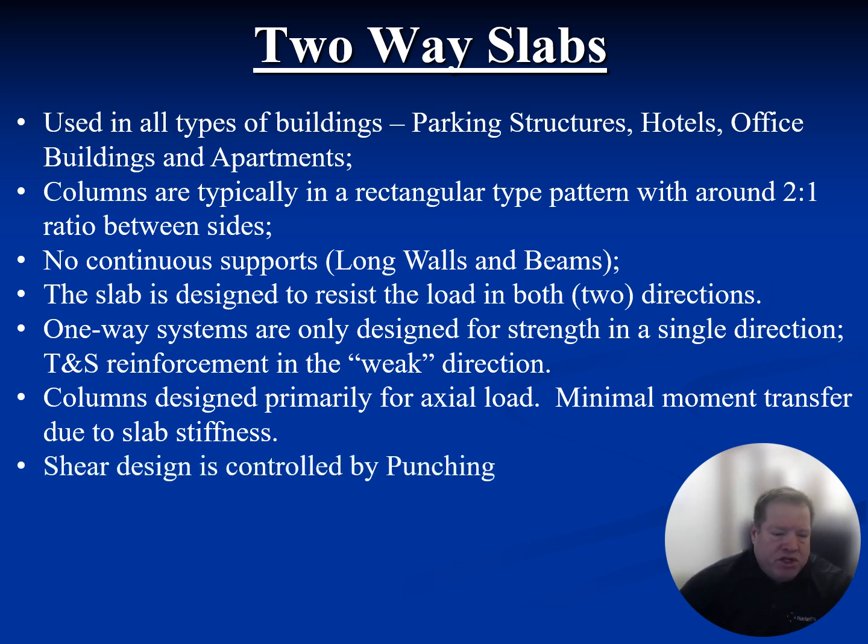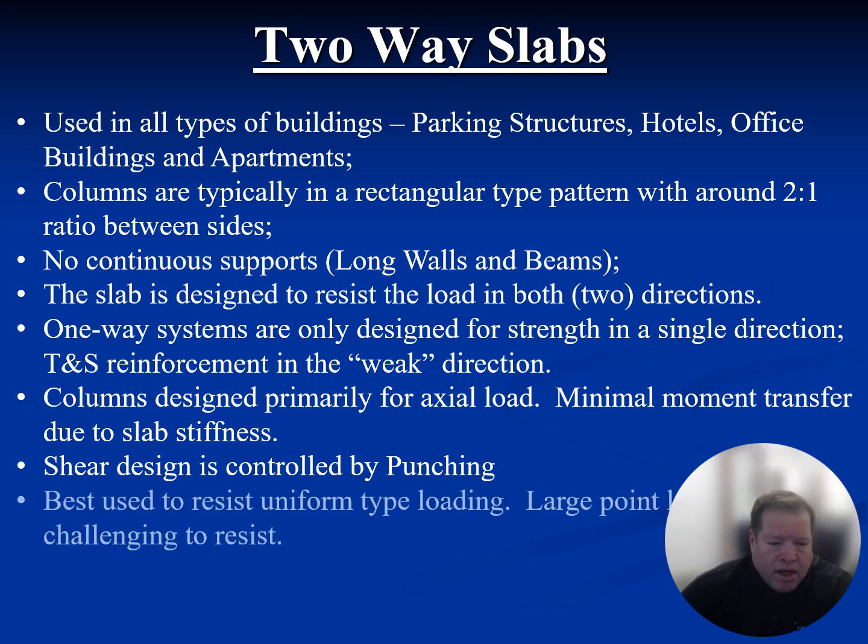The other difference is shear design. The VCI, VCW, VCN equations do not come into play for two-way slabs. It's controlled by punching shear. And so those equations are going to be different because obviously it's a different methodology, a different mechanism.